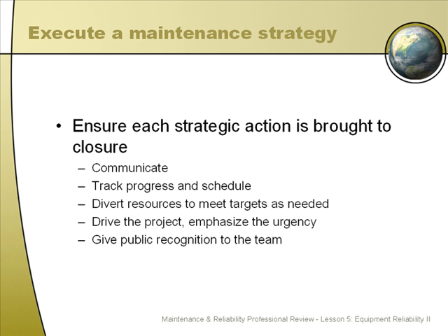So much of the time in a reactive maintenance organization, all the credit goes to people that fight the fires and solve the problems when you have breakdowns. You need to really get away from that. When you have breakdowns, it's something that you should be ashamed of, not something you should celebrate. So if you break down and you fix it, tell people thank you for the help in fixing it up, but don't turn it into a big glamorous event. Make sure that the people that get the credit are the ones that avoid failures and the ones that solve problems so that failures don't occur anymore.